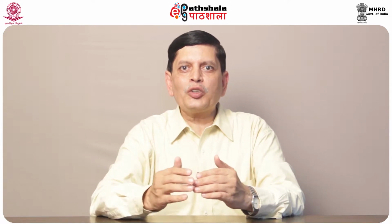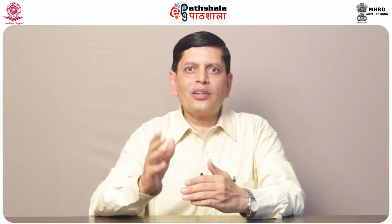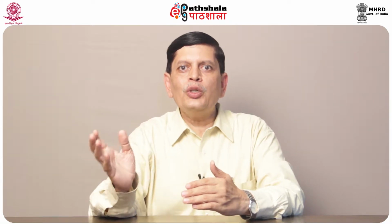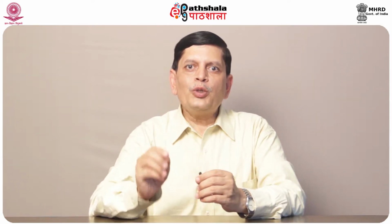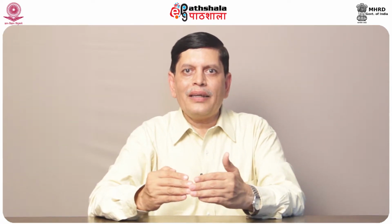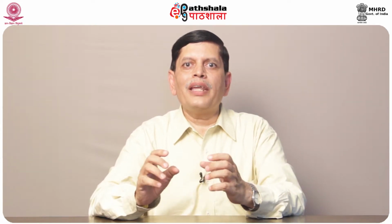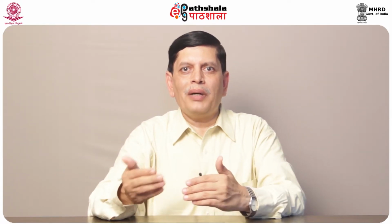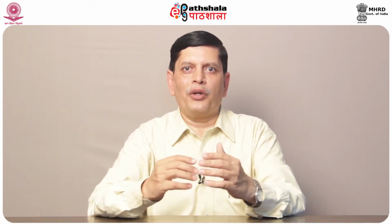The array matrix consists of rows and columns. The rows are the outputs of the decoder, whereas the columns are usually connected to the pull-up resistor. These pull-up resistors are connected to VCC or logic 1, and whenever we talk about such a configuration, usually we take the output from the OR gate. So, whatever the terms present in the sum, those min terms are added together and the output is taken from the OR gate. So, we have an AND and OR plane. The OR plane is programmable and the user can program it whenever required. So, this concept will be explored in this module.